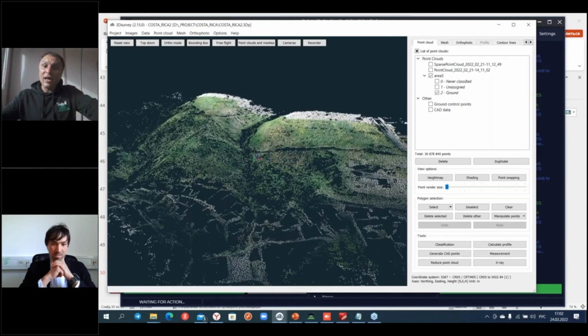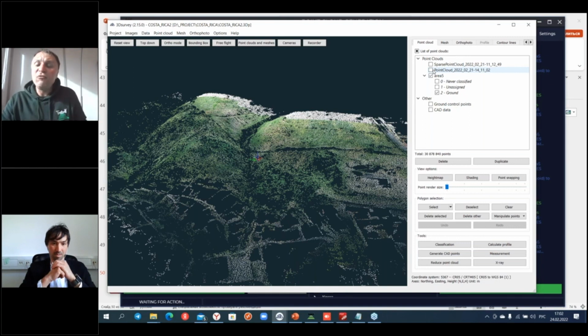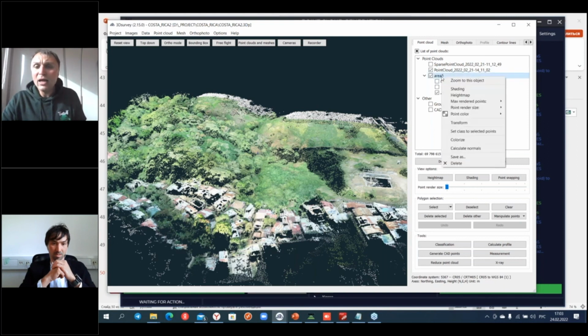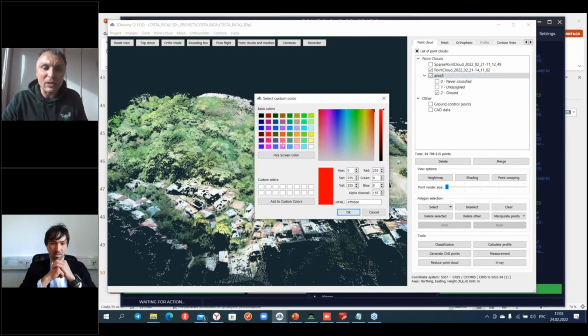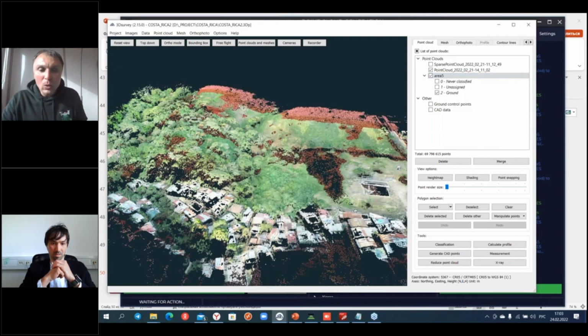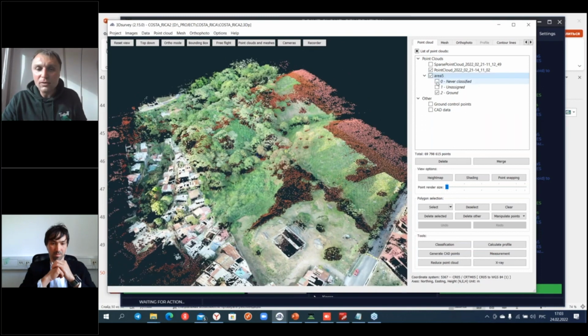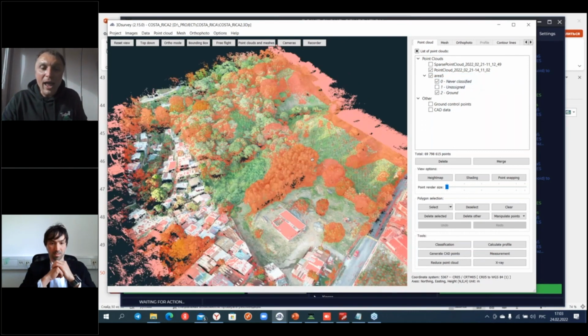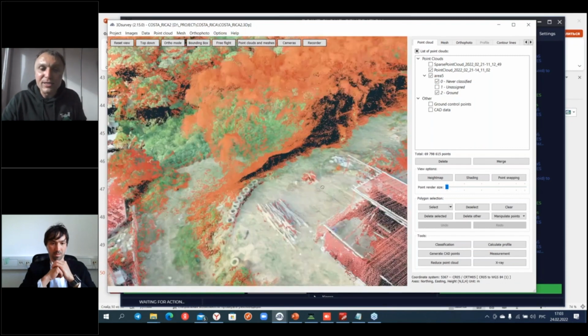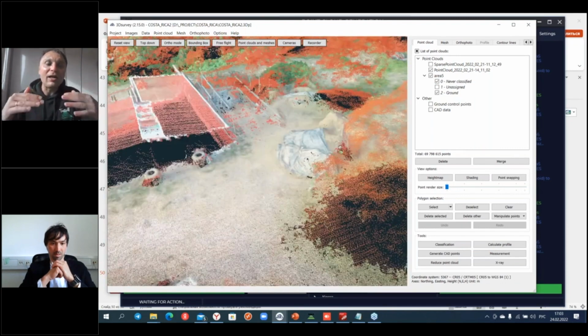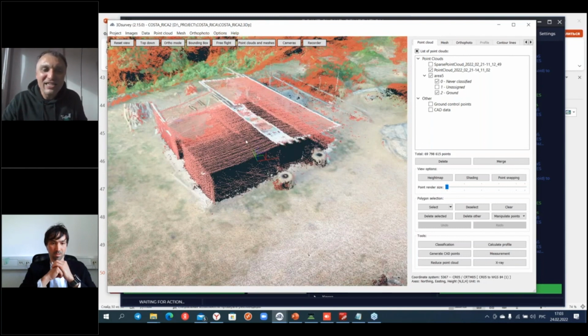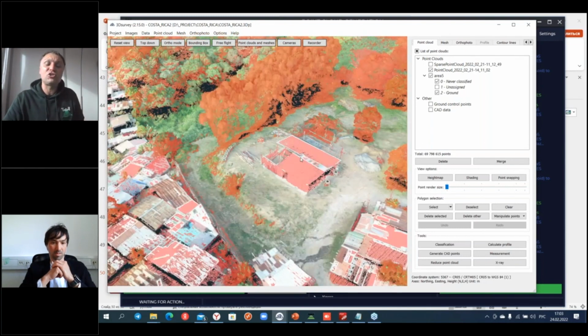And right now, as soon as I add our point cloud, we can compare the accuracy of the point cloud in comparison with the accuracy of photogrammetry. Before, I just generated a point cloud from photogrammetry, this one, and I will change the representation of the LiDAR point cloud to another color, let's say red. After that, we can easily check the 2 point clouds I aligned. And you can see that it is amazing accuracy, all point clouds are combined together without any difference. And this is a major advantage of 3Dsurvey.